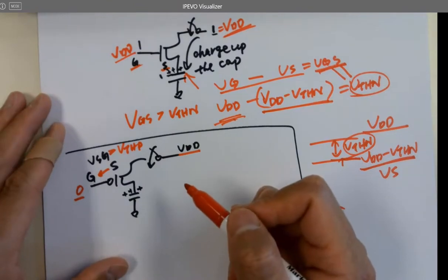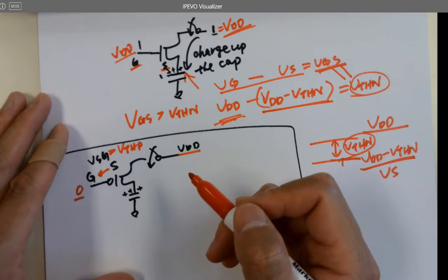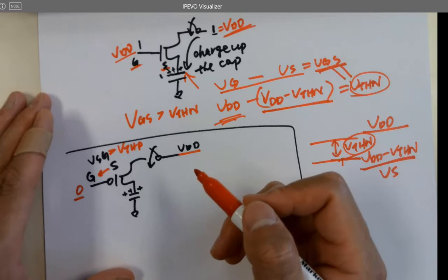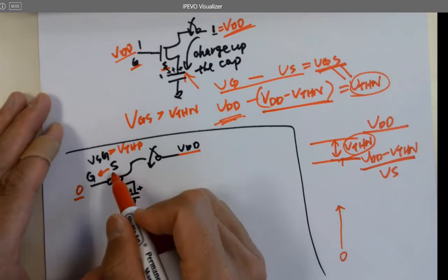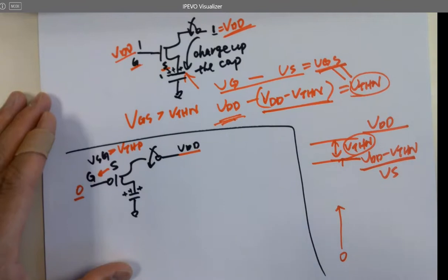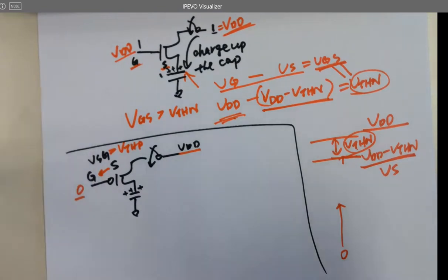I'm still processing. You need a logic 1 to turn on the NMOS. Yes. Logic 0 to turn on the P. Yes, to the gate. You are looking at VSG or VGS, the potential drop, not the absolute voltage at the gate. So if you have 5 volts at the gate for the NMOS, and you have 10 volts at the source, it's not going to turn on.